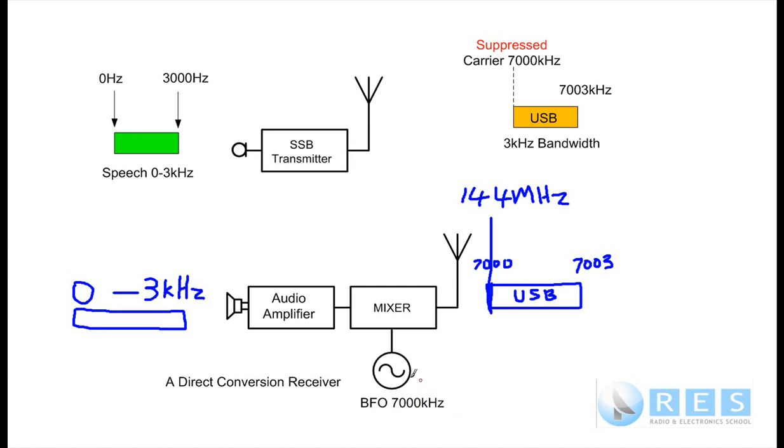And for amateur radio purposes, direct conversion receivers are really handy for simple little receivers to monitor transmissions on, or for Morse code reception. But because the BFO, which is just an oscillator, has to be on such a high frequency to receive high frequency signals, the BFO tends to drift and wander in frequency a little bit. So they're not that popular in more sophisticated amateur radio equipment.